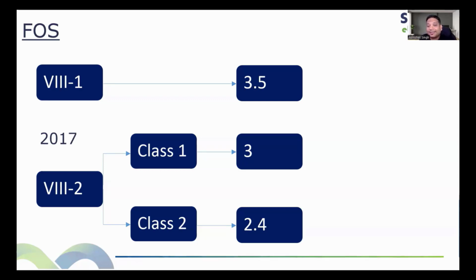See the difference. We are talking about all these differences. For Class 1, you cannot overrule the thickness, similar to Division 1. In Division 1, if the formula is available, I cannot use FEA to optimize the thickness.